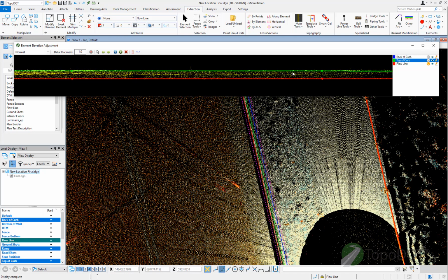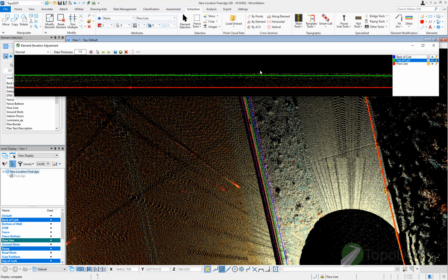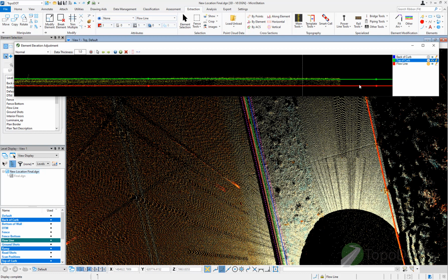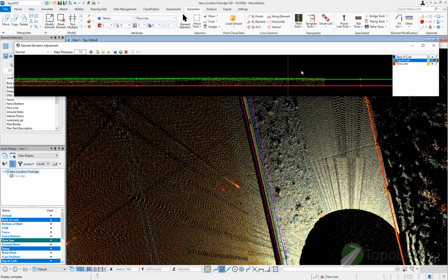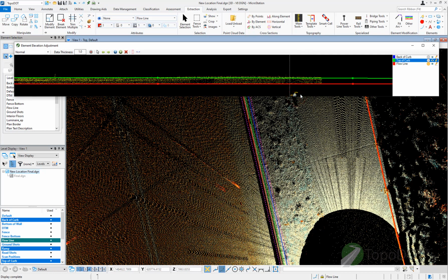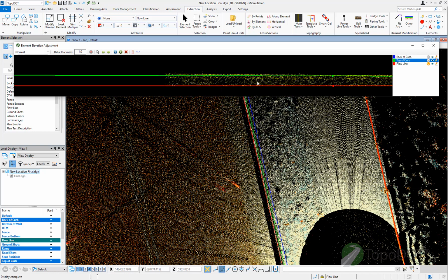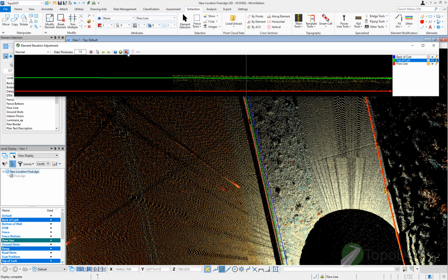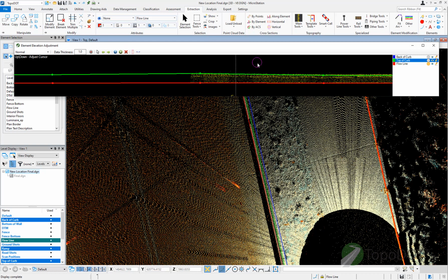And you can quickly address those or see them happen because the lines kind of help you project and visualize it. So for example here, I can see that there is a little bit of an offset there for the top curve, and the next point is okay but not in between, so I can always insert a node right there and adjust, move my top of curve and back of curve, and to introduce that change.